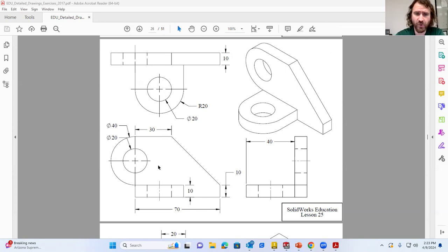So we look at our top view and our front view. And in all honesty, the top view is okay. There are not as many dimensions there, which leads me to think the front view is going to be our choice, because there are more dimensions. But there's another reason why the front view is my choice in this particular situation. Even though the top view isn't bad, it's got the circle and this visual information here that we're going to have to do regardless. We're going to have to cut out regardless of which we choose.